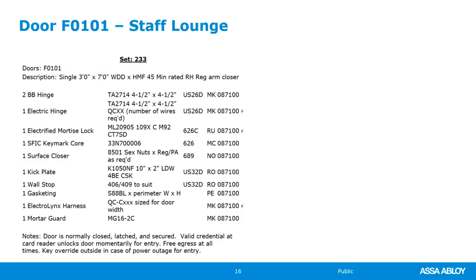The question is, can I discuss electric strike versus electric lock on this opening? Was it an owner decision? In a brand new facility, especially a hospital, electric strikes are more for traffic control than they are access control. If this were a retrofit, then an electric strike could be a very viable option.